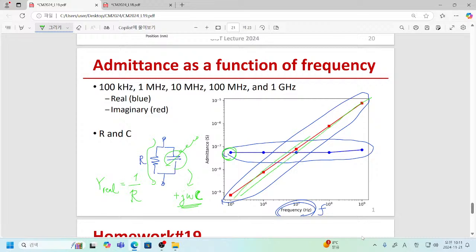So what people do with this TCAD simulator is to make a certain structure whose DC characteristics are well matched. After that, apply the small signal analysis and extract certain Y parameters. In order to match these Y parameters, introduce a small signal model like this one for a simple case, and try to find parameters like R or C to match the expected behavior of our circuit. So this is used to match our device characteristics in the RF frequency range with a compact model. So we must put some effort into this one.